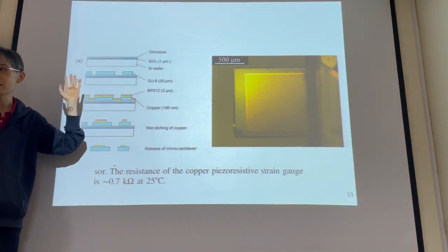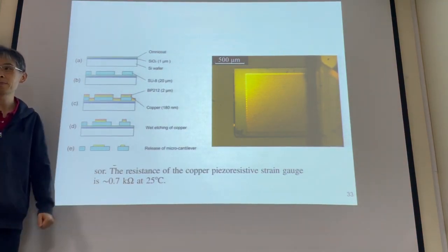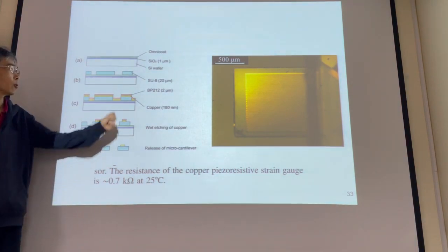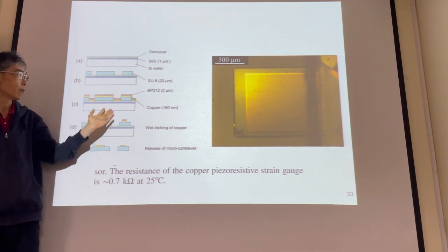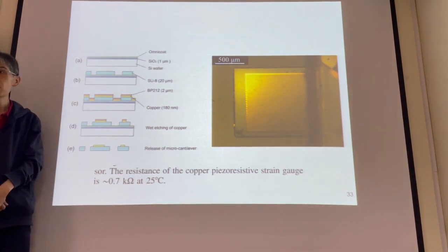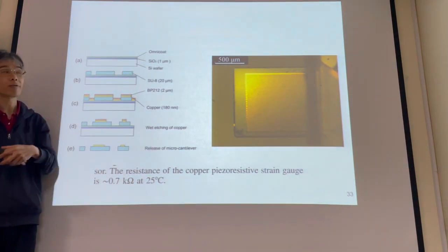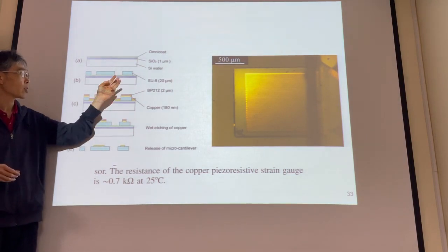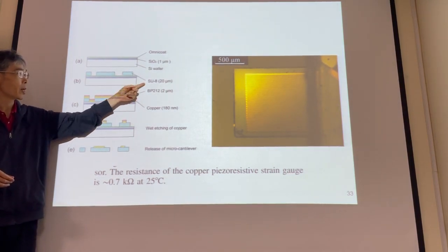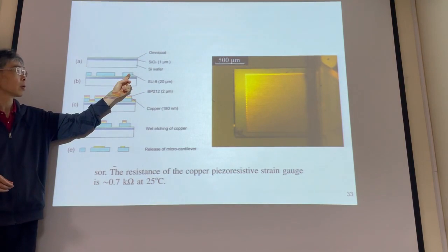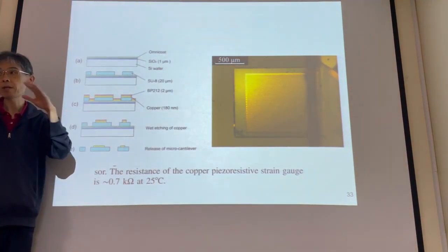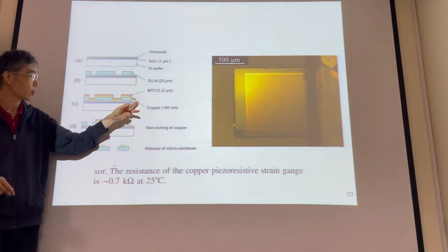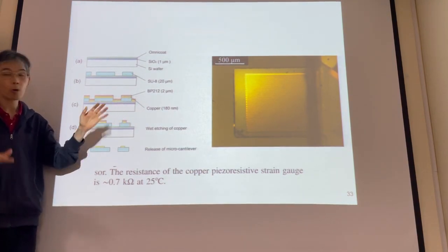Okay, let me ask Frank, why do we need this undercoat layer in this fabrication process? Because, okay, let me explain the fabrication process. So on top of the undercoat, we can pattern SU8, the polymer. Then we just use, say, sputtering. We can sputter copper, the yellow, all over the wafer.